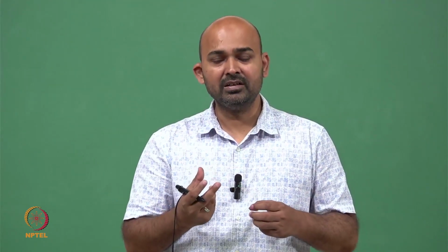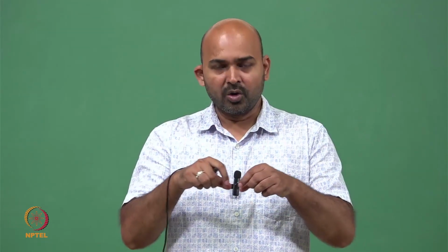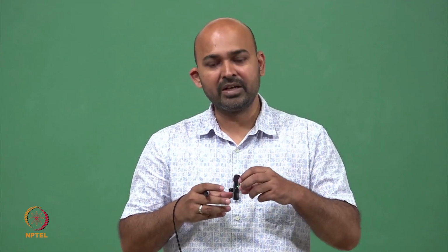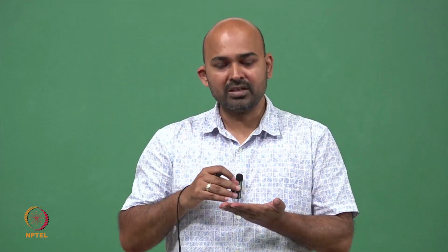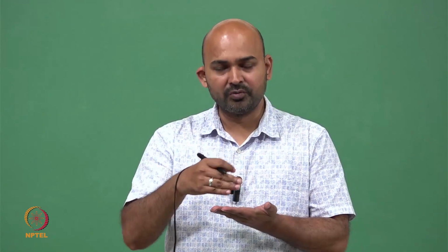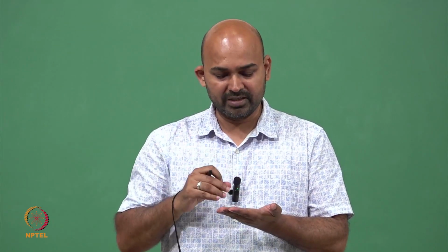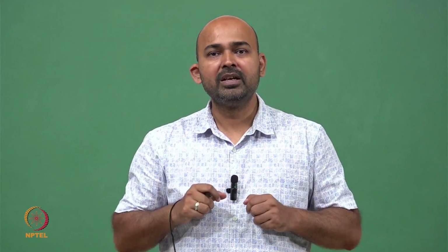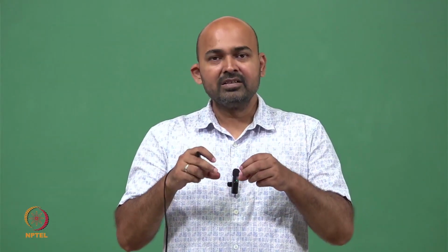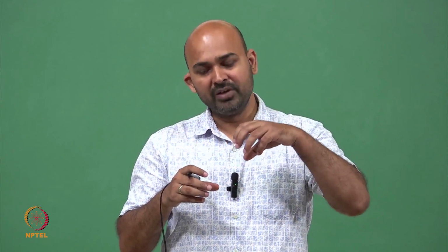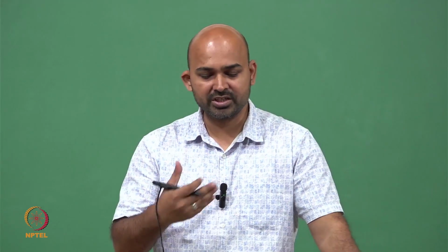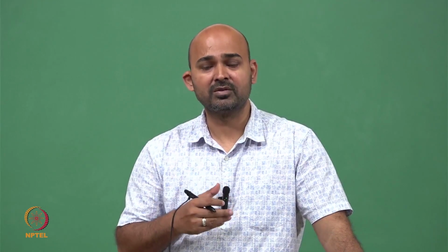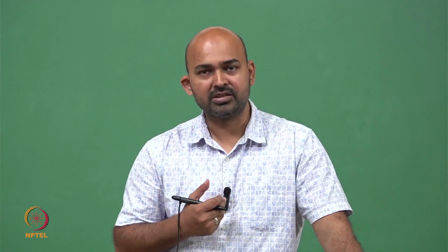For example, let's say we have a silicon substrate, and on top of it we deposit these magnetic materials as a very thin layer using metal deposition, and then we do photolithography to etch out the extra material, and we pattern these magnetic materials on the silicon. That is our sensor. Now we apply a magnetic field on this patterned magnetic material and see how much is the change in the property, for example, the resistance of this material. So let's see how we make this sensor.